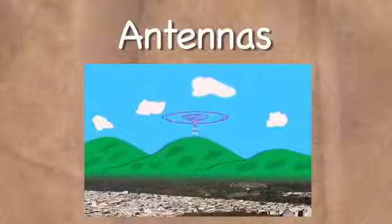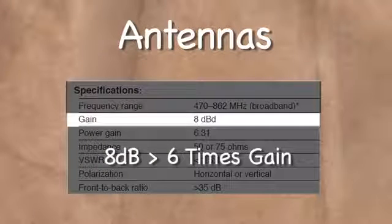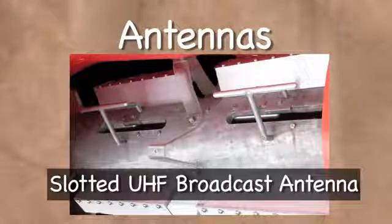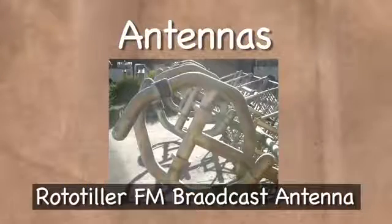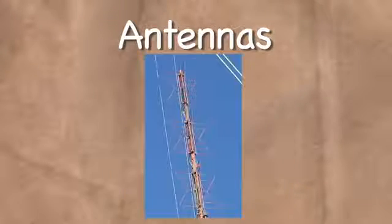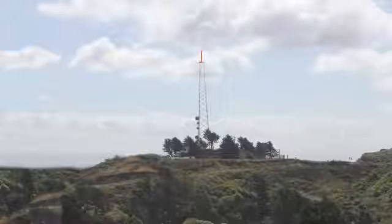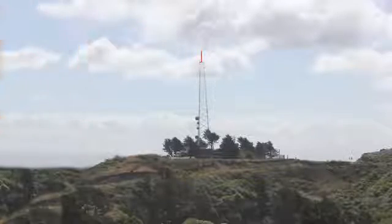Antennas emit and/or absorb radio waves. Based on their structure, they can shape and focus RF waves, providing gain or amplification to the signal. The antenna, its apertures or elements, must match the wavelength to efficiently pass the radio waves through it. The better the match, the higher the efficiency. There are many different designs for antennas, from a simple wire hung between two trees to a broadcast antenna that weighs several tons and costs $250,000. Some are as tall as towers, and others fit inside your cell phone. Their shape and size all depend on the wavelength used and the purpose of the antenna.